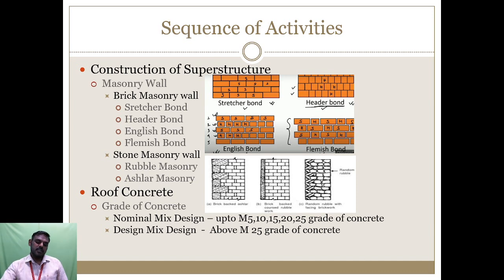Okay, this is based on the coarse aggregate, fine aggregate and binder. Binder means cement. Based on these properties, in addition to that the water cement ratio, the design mix will be decided. So these are the factors we have to maintain for design mix concrete.